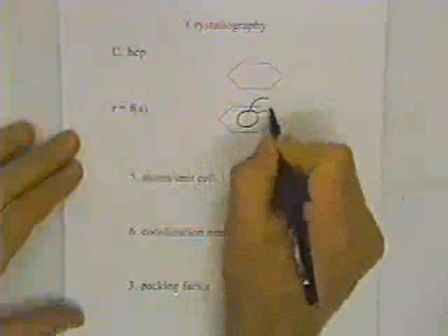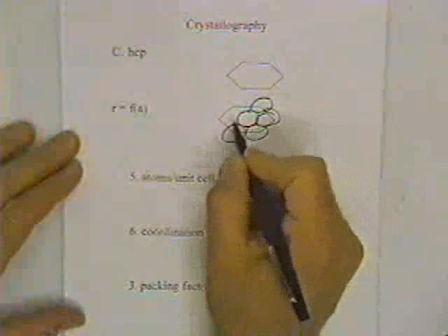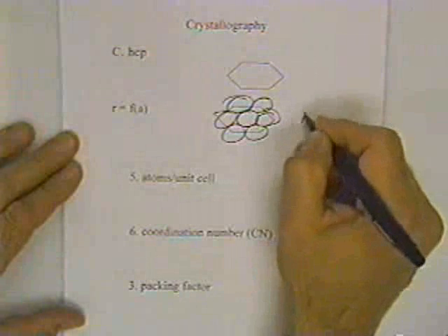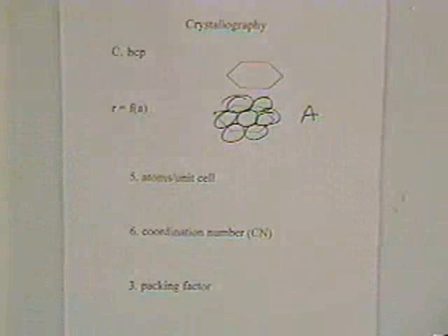Now the other crystal structure that was in the workbook, or the booklet that you can take to the test, is the hexagonal close packed, and there's a couple ways you can represent this. This is called the large unit cell, and you can think about it as being a hexagon, and we're going to put a close packed plane, we can designate that close packed plane as an A layer.